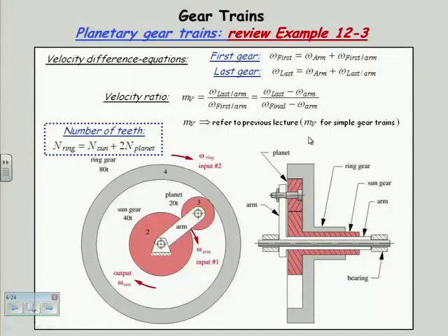And typically in these situations, the second input to one of those two things is 0. So if I lock, let's say, the sun to ground temporarily with a brake, then I will get a certain ratio. And I showed you in the kinematics class, if you took that with either me or Professor Van der Ven, you saw how we can get both forward and reverse motion out of this thing by locking different pieces, and how we can get quite a variety of ratios.